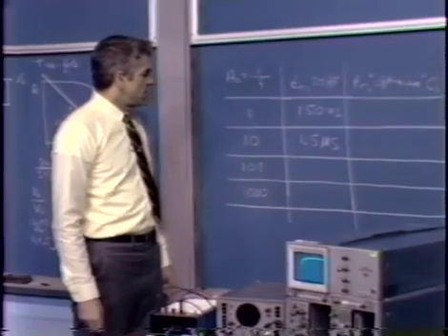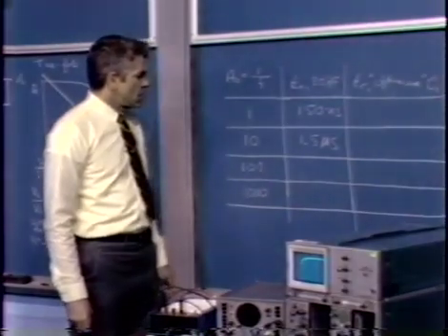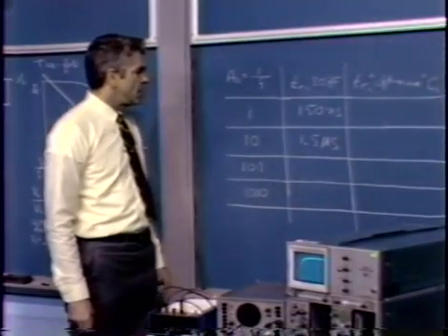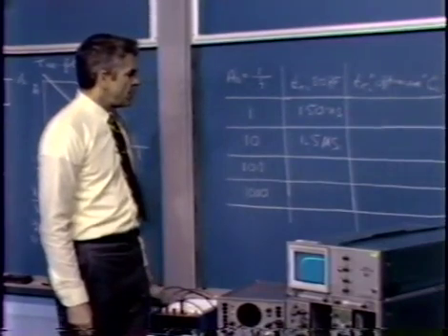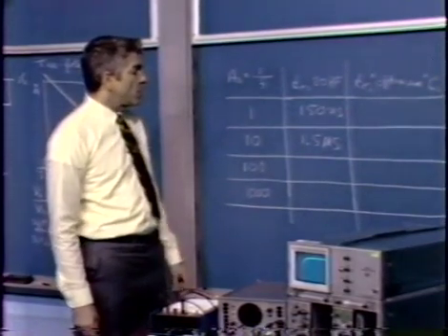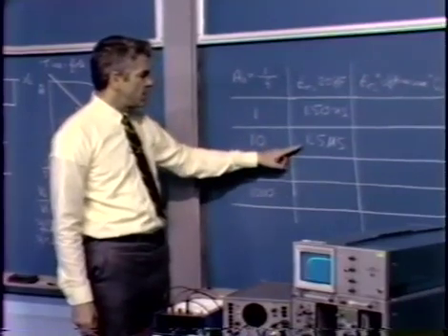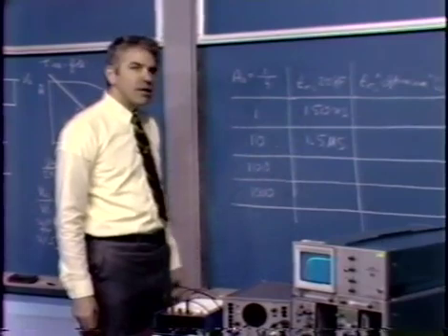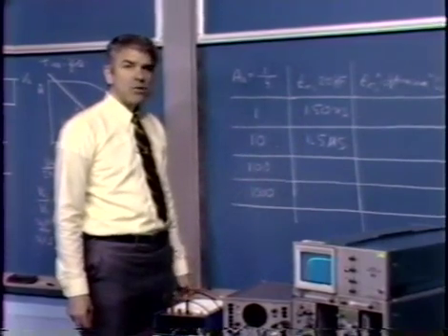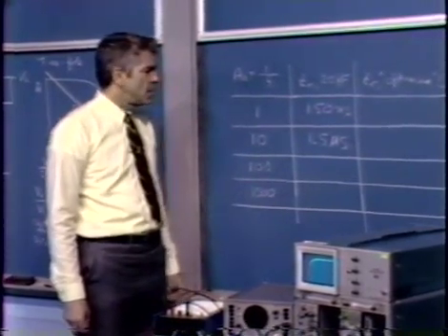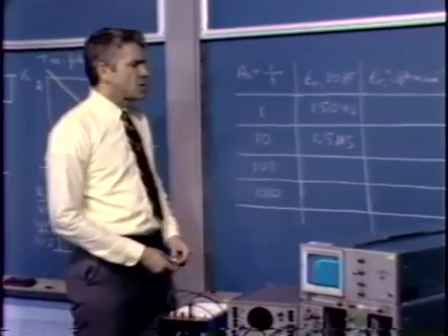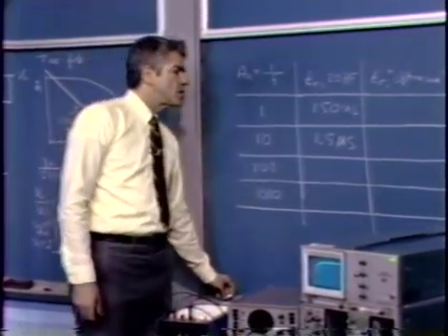We found out that the time constant associated with the closed loop gain was proportional to the ratio C sub C over F. Here we've kept C sub C fixed. We've changed F by a factor of a tenth. We'd anticipate that the closed loop response would slow by just about that factor of 10, and in fact it does. We also notice a little change in the character of the response.